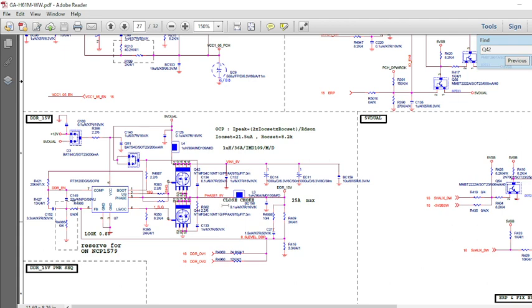Again, I have told you the pin numbers of DDR3 RAM. So you have to check those voltages, such as RAM VTT, SM clock, SM data, and SPD VDD. You have to check them on that RAM. And for checking the DDR supply, you can check on L3 or the drain of this Q44. This is the section where you have to check your RAM supply. Next, this is the first signal which you have to check.